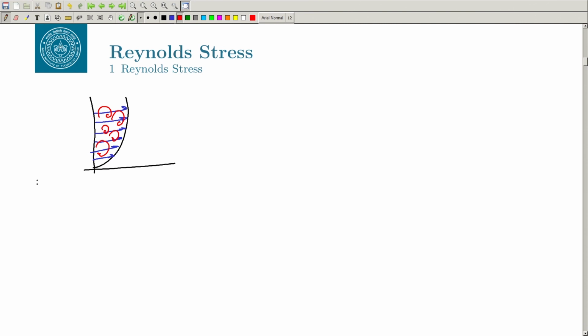If you take a typical fluid element, let us say you take the element somewhere here, or maybe somewhere here, and blow this up, this is my fluid element, and this is how it is being cut. You have a velocity gradient, because this is a simple shear flow, you have this del u bar by del y. So, that gives you a stress, mu del u bar by del y. So, this will be tau equal to mu del u bar by del y.